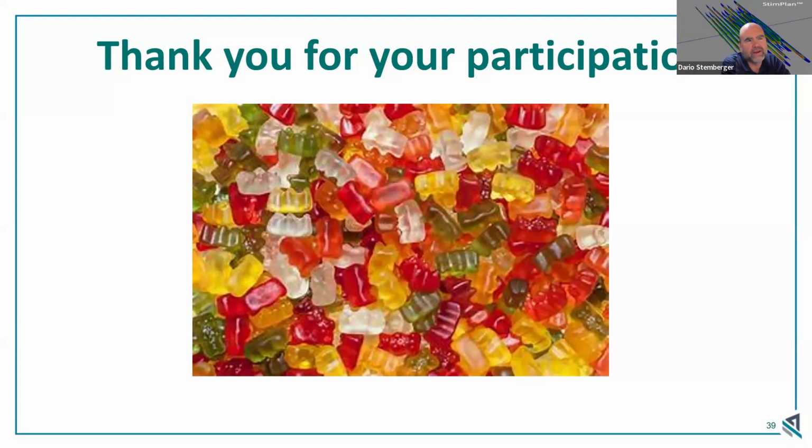Have you tried non-ionic FRs? Yeah, and everything's a give and take. There are non-ionics, but they haven't in the past performed as well on your friction reduction characteristics. They may work, they may not give you what you want from a performance perspective, especially when you're dealing with brines. In high brine scenarios, if you're in fresh water, they may work, I don't know. But most people in the industry use acrylic based.